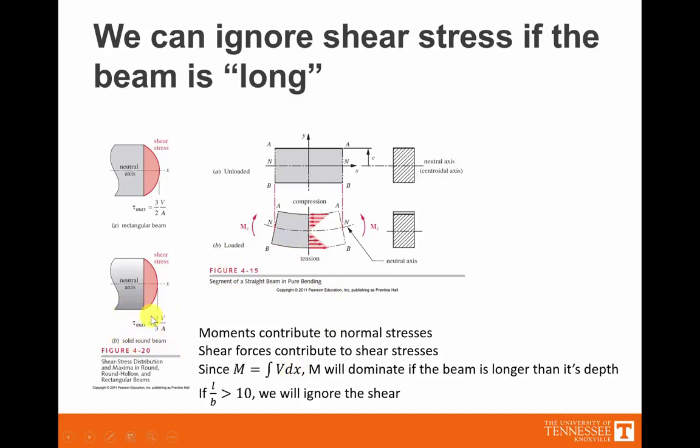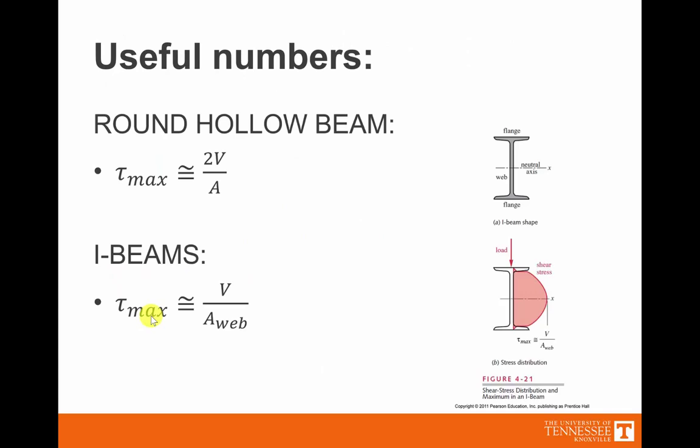Although it's very unlikely to find beams in practice that are loaded in pure moment, a lot of beams are 10 times longer than they are thick. Since the beams are so much longer than they are thick, the moment is going to be the driving force of the maximum stress inside the part, and we don't even need to consider what the shear forces are contributing.